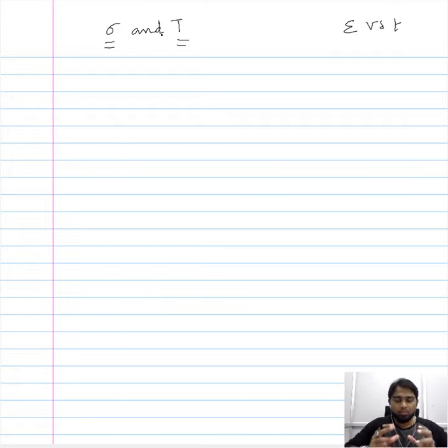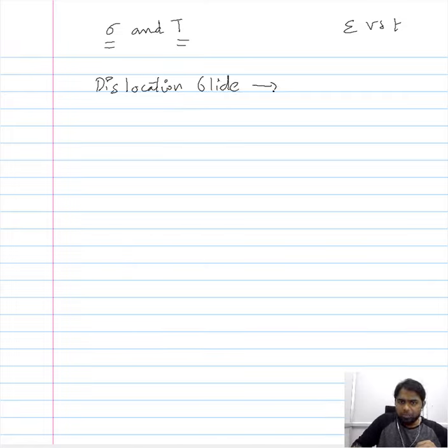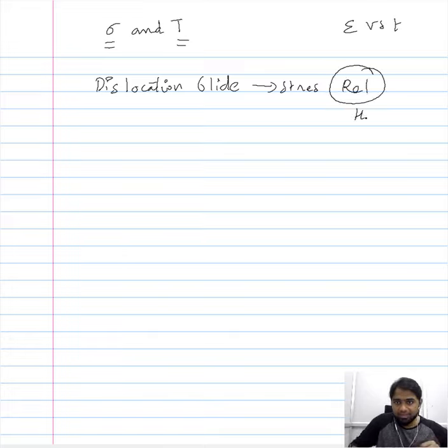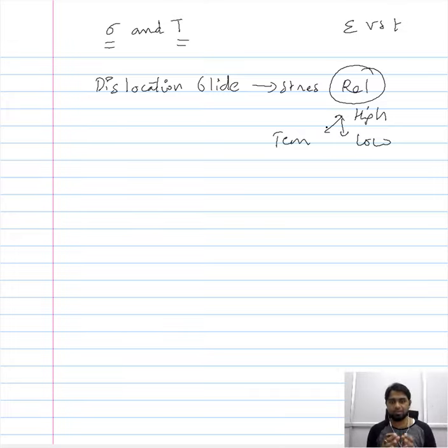We saw two different types of creep mechanism in the previous lectures. So one of the creep mechanisms was dislocation glide. So this particular creep mechanism is prevalent when the stress is relatively, the key word is relative here, relatively high, or the temperature is relatively low. So again the temperature is relatively low. In this case the mechanism that is operational is the dislocation glide mechanism.